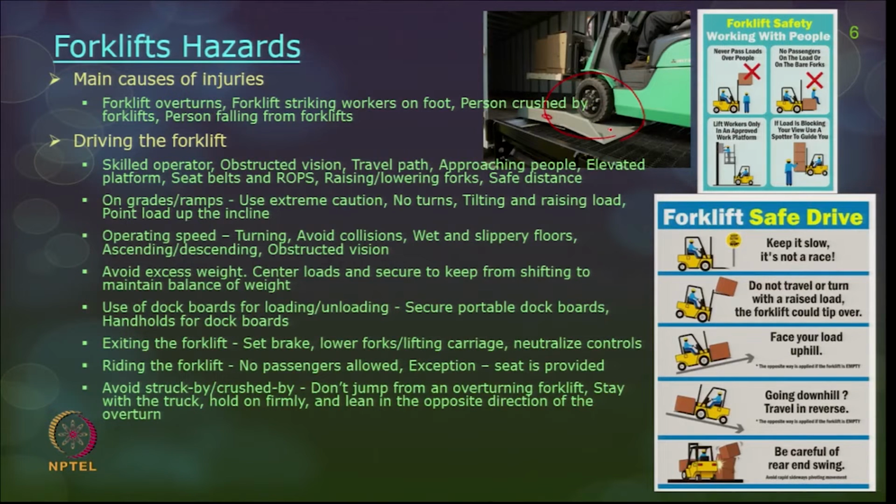Riding the forklift, no extra passengers are allowed. Even if there is an exception for unloading or for movement of material, then a seat should be provided for the extra passenger, and otherwise no extra passenger is allowed inside a forklift. Avoid struck by or crushed by. Don't jump from an overturning forklift. Stay with the forklift truck only, and hold on firmly, especially when it is about to overturn, and then try to get down from the direction opposite to the overturn, so that you are safely away from the forklift.